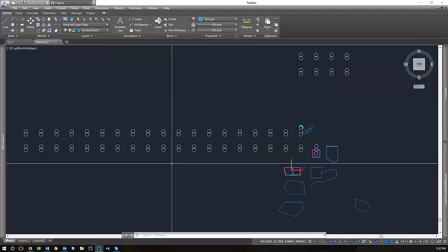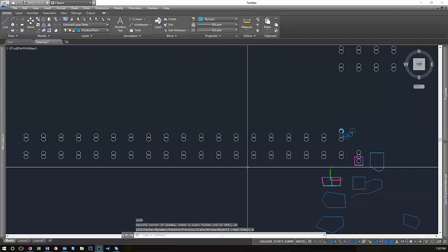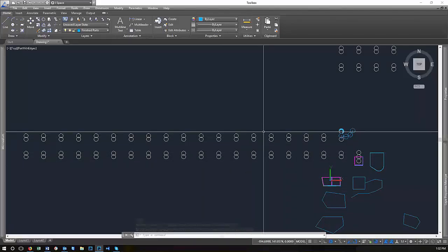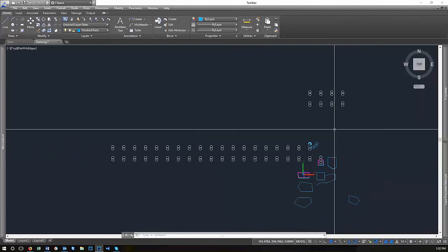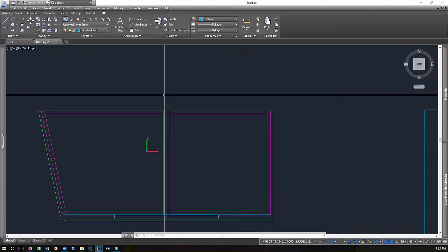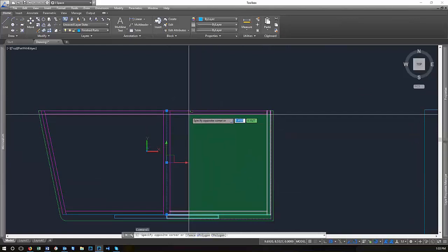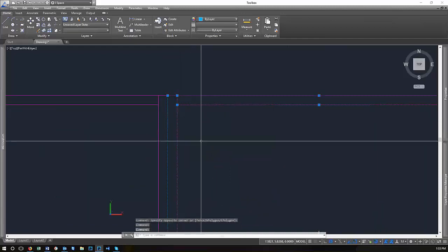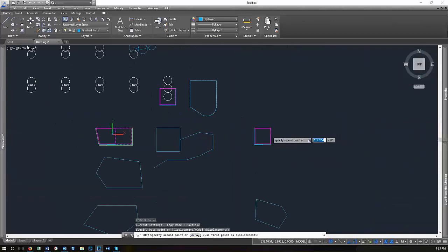All right, so moving right along to blocks. Blocks are a unit of your drawing. It's a way to group parts and simplify things. So if I use this cabinet over and over again in a job, sorry, use these objects, because if you're using an actual cabinet drawn by Microvellum, you would do it a different way. But if I was just going to use these AutoCAD objects, these lines, I'm going to copy it out and put it somewhere else so I can work with it.